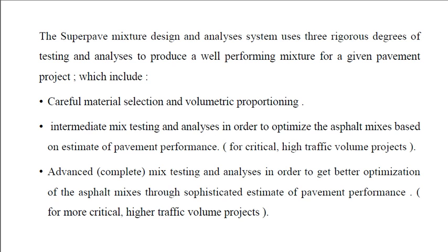The superpave mix design and analysis system uses 3 rigorous degrees of testing and analysis to produce a well-performing mixture for a given pavement project, which basically includes first, careful material selection and volumetric proportioning; second, intermediate mix testing and analysis in order to optimize the asphalt mixes based on estimates of pavement performance; next, advanced mix testing and analysis in order to get better optimization of the asphalt mixes through sophisticated estimates of the pavement performances.